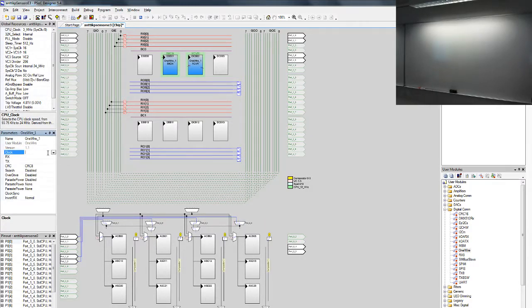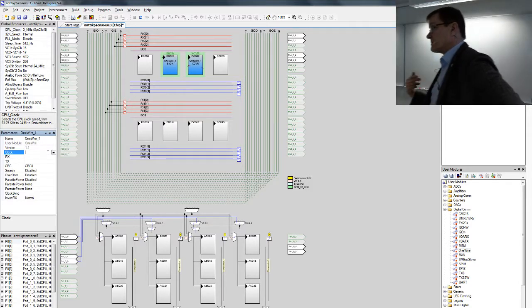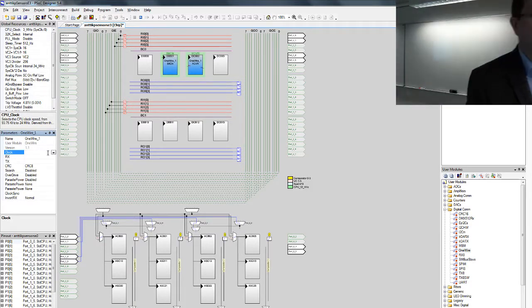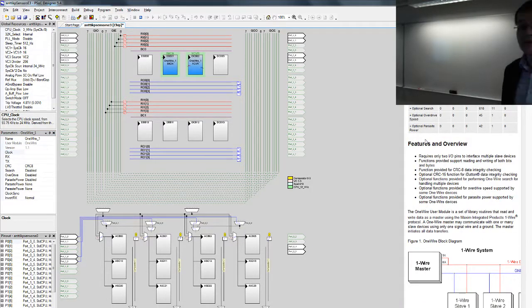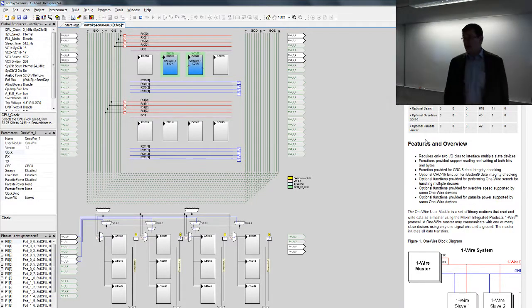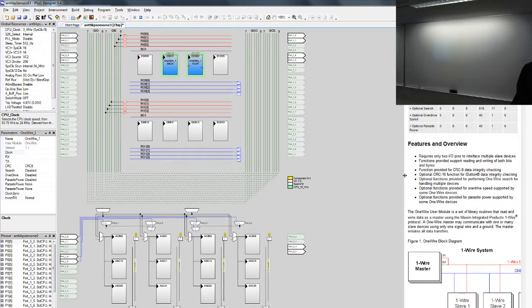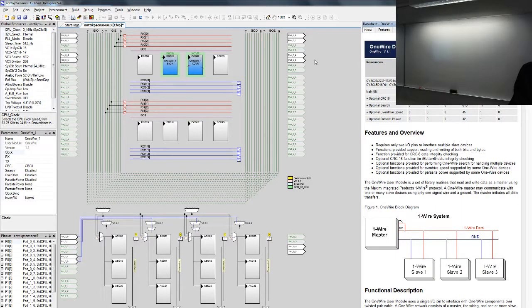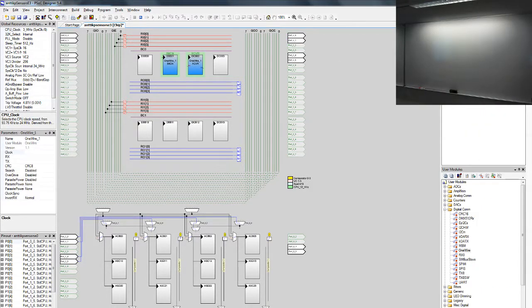And you just need to set up the clock according to the specifications. So there you need to basically compare the datasheet of this PSOC OneWire module with your device. I think there are pretty good examples of how to use that one. Okay. And just configure and then find a way, which is also in the application notes, how to use the same pin for input and output.